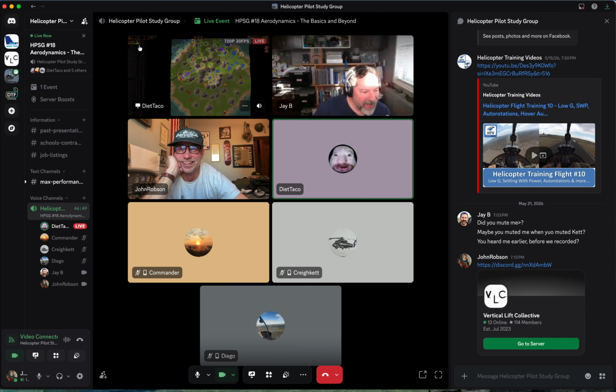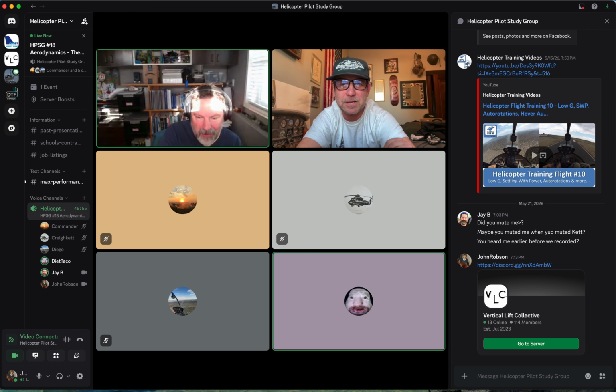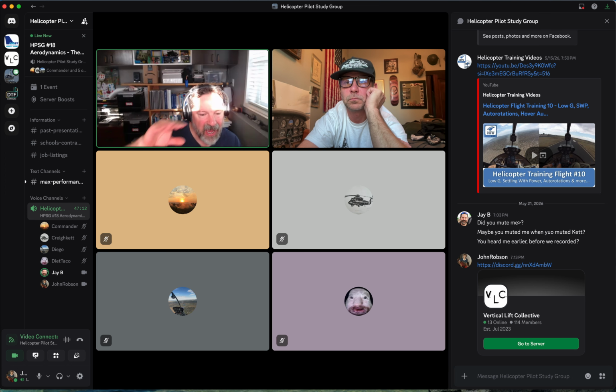Hey, John, one thing I did want to talk about, when you were talking about asymmetrical and symmetrical airfoils. There's a minor correction there, I would say, because the main rotor airfoil of the R22 and R44 being symmetrical is not standard. Pretty much everything I've flown other than a Robinson has an asymmetrical main rotor airfoil.